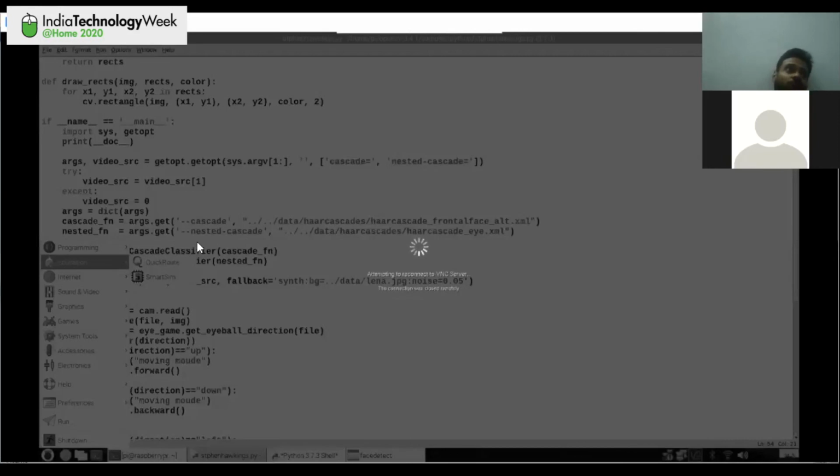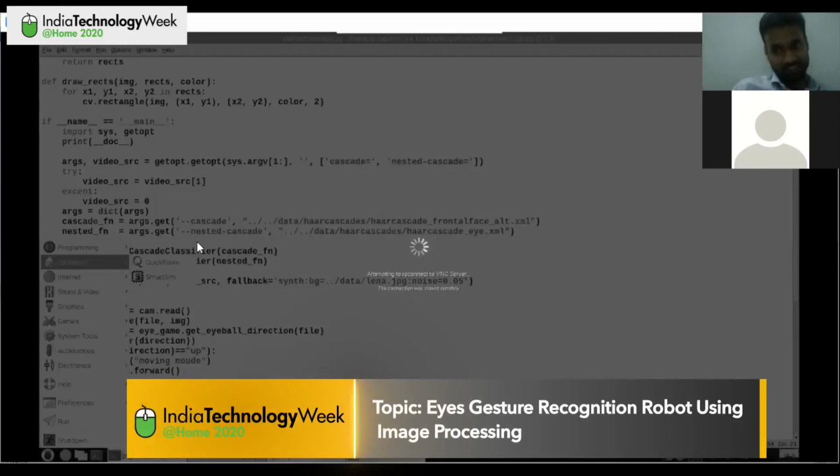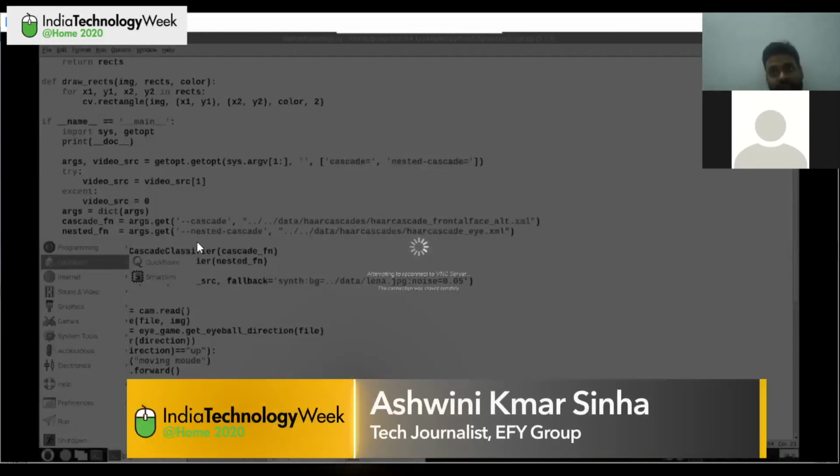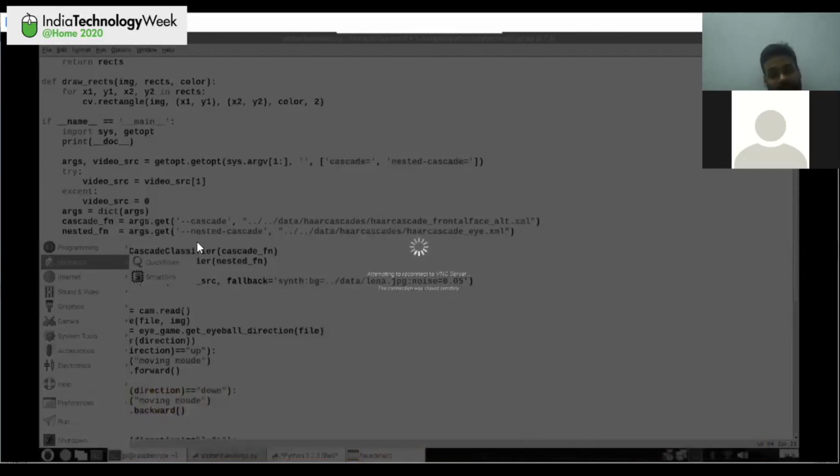It might not burn the Raspberry Pi, but it will shut it down. So you first have to decide the requirements of the project and how deeply you are going to use OpenCV and processing power, and select the Raspberry Pi board accordingly. For high end processing, Raspberry Pi 4 with 4 GB RAM is better.